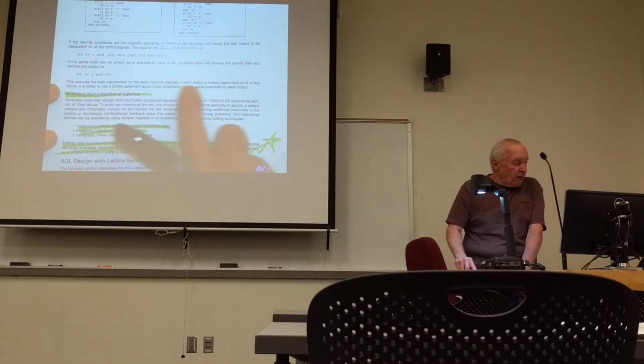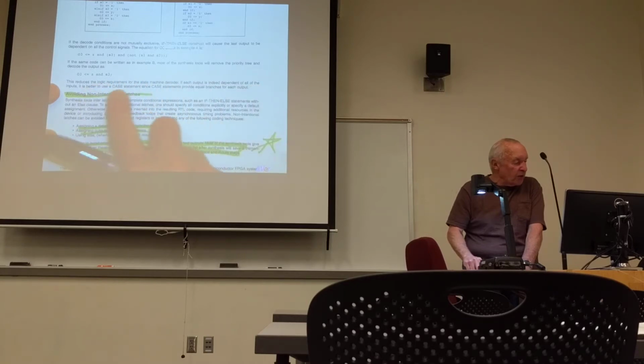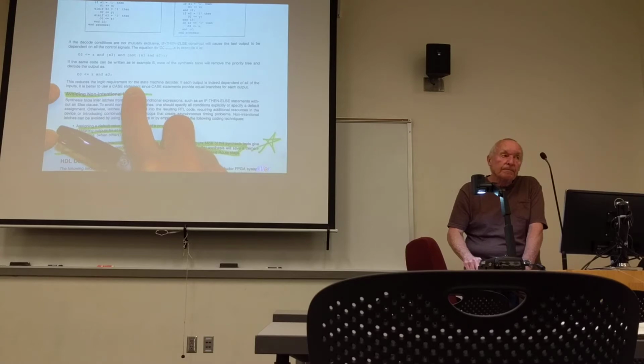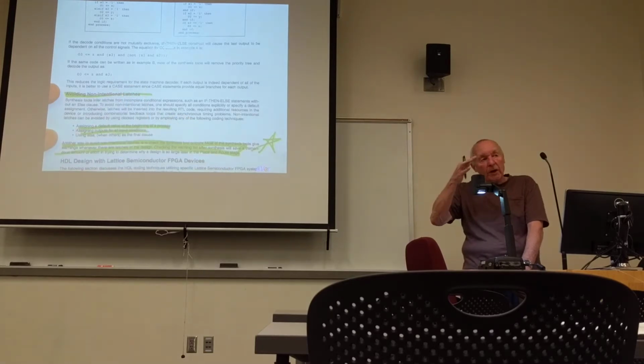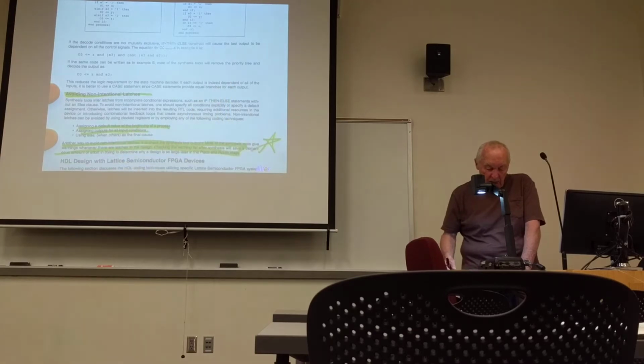If each output is indeed dependent on all of the inputs, it's better to use a case statement than an if-then-else statement. So you have your choice of encoding it either way, and you're going to get the same functional behavior. But they're recommending that under this circumstance, you should be using a case statement.